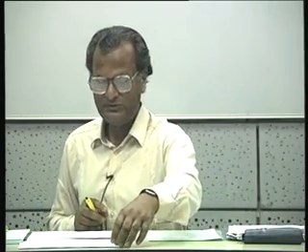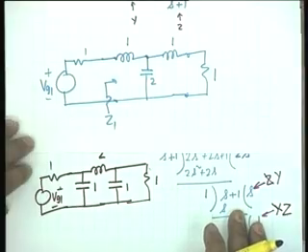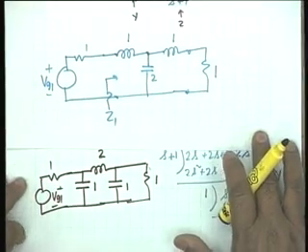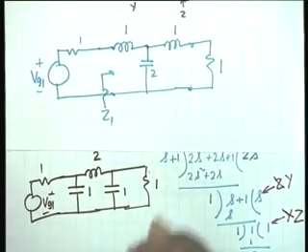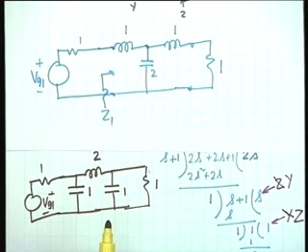I must tell you, you may not be that lucky in the general case, but how to get over it we shall discuss later. I want you to notice two important facts. Can you see on the monitor both of these networks? You see both of these networks share something in common. What is it? That the inductors are series elements and capacitors are shunt elements. Isn't that right? And I said the given function was a low pass function.